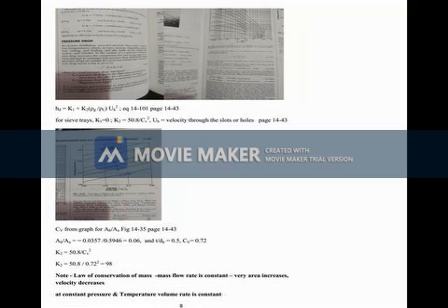What is FLG? FLG is a flow parameter. You know all the values. L is known, G is known. L and G are the mass flow rates. So you have the molecular flow rate; you multiply it with the molecular weight and convert it into mass flow rate. That is shown here. Then you find out the value of